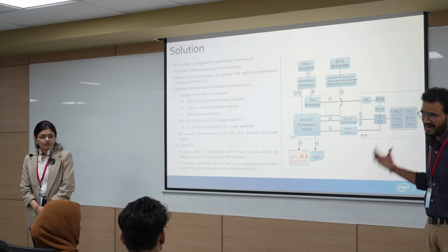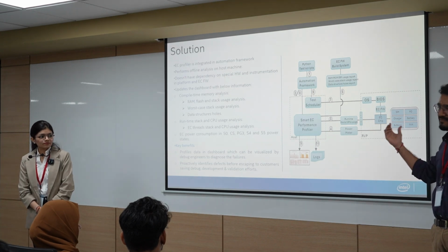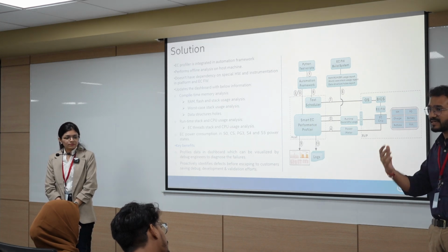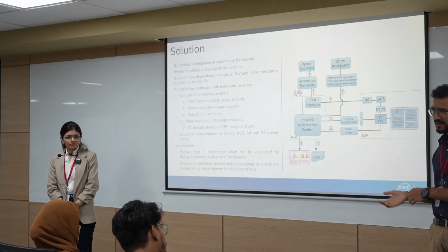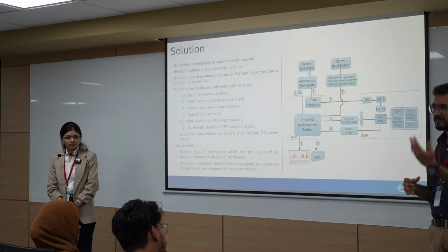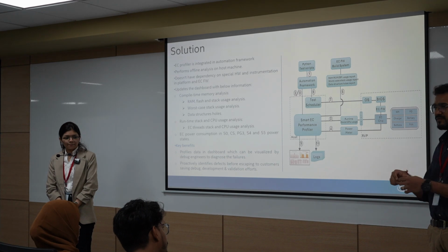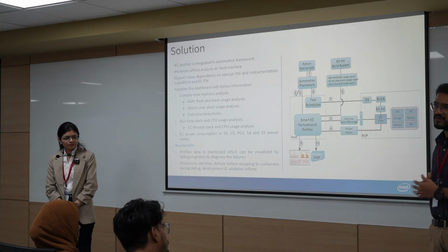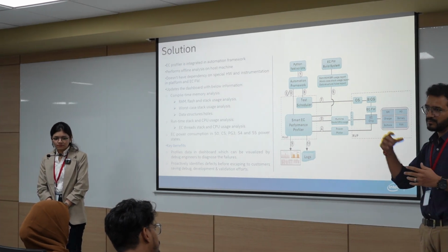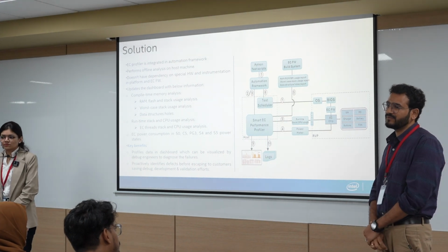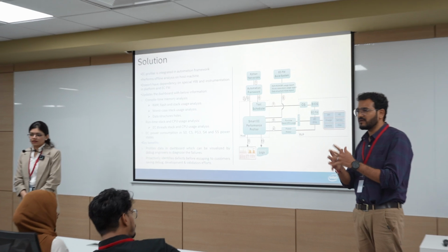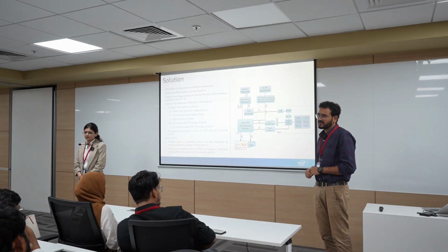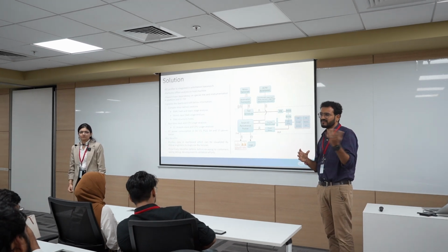Supported on the EC hardware. What we are doing is this will give a developer an insight that this is the amount of RAM or the stack that is really being utilized by the application. If we need to support some new application or any new implementation, we need to go for a higher version EC chip. There you have even more RAM or capacity, so that we can add more new features. So this will give an insight to the developer: we are running out of memory, so we need to move to a newer version. Like that only we did previously. It was a different series altogether.